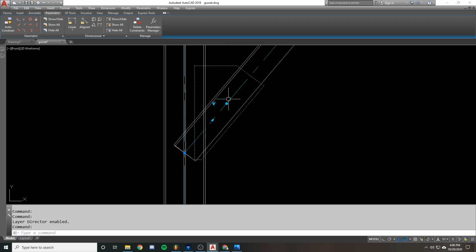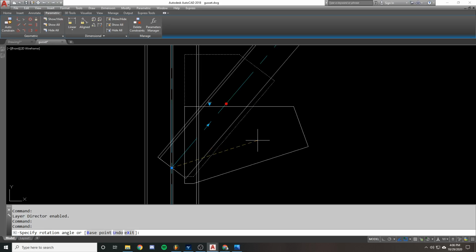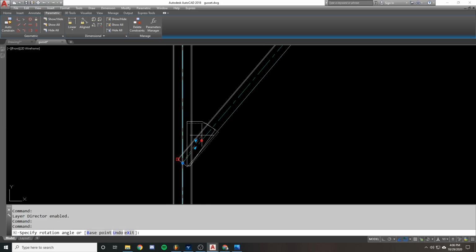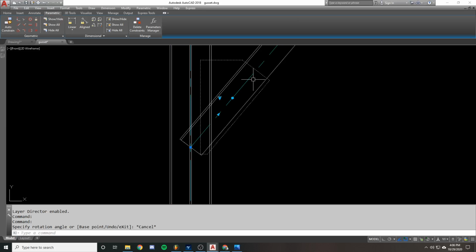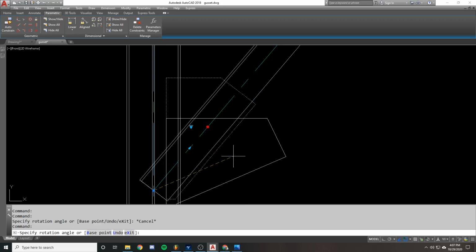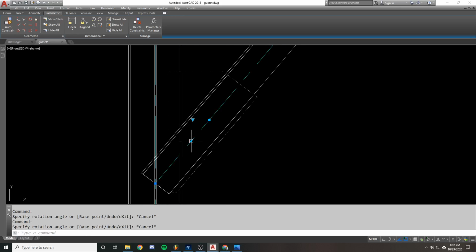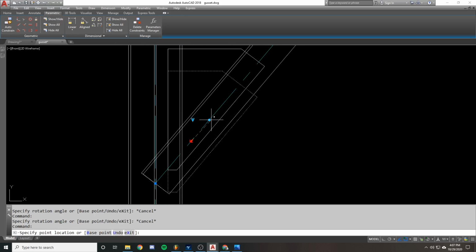And what this block does is I have a rotate parameter, and as I rotate this gusset plate around, it changes in shape. This was to allow me to change the angle based on the angle of the brace. And you can see as I change it, pieces of it are extending and shortening and changing their angle, which is really fantastic. So I've got certain parts that are fixed and certain parts that are movable. I've also got some extra parameters, like allowing me to stretch out.